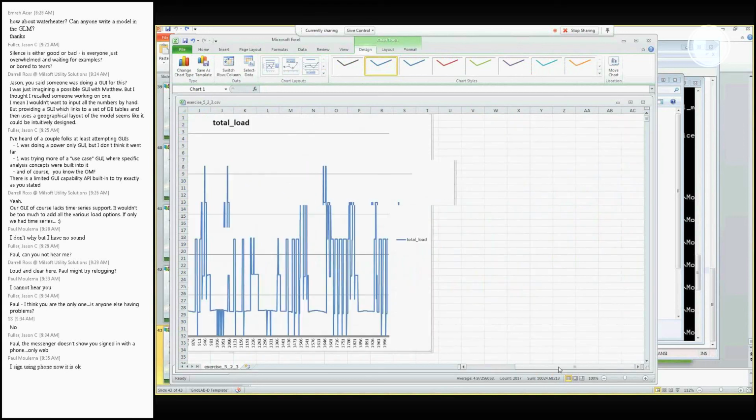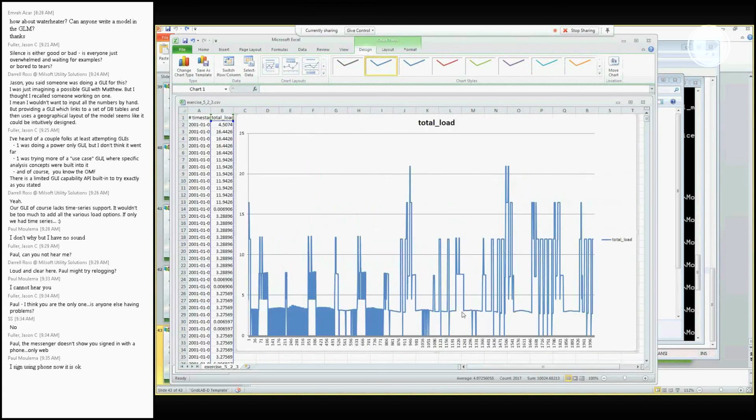So it's getting to be a little bit nonsensical as a house right now. But you can see what ends up happening is the key point to why we do all of this the way we do, is that when you look at the load of a house, it's not a nice smooth shape. It's definitely not a single value. It's a series of pulse trains that, as you move through the day, either elongate or tighten, depending on what is being driven, what loads are coming on inside the house.